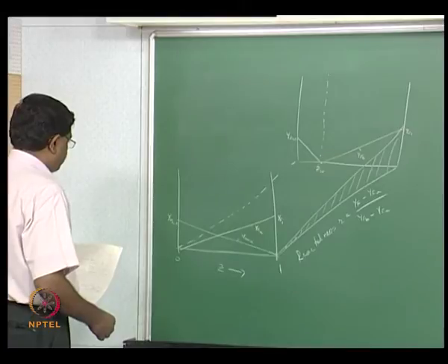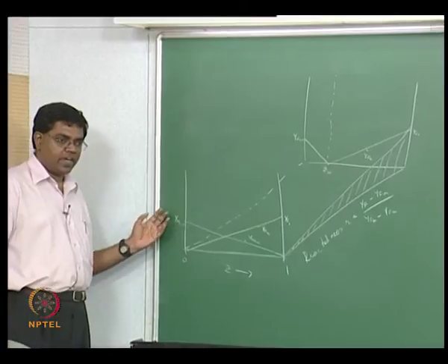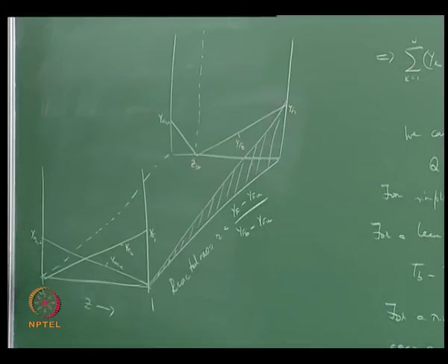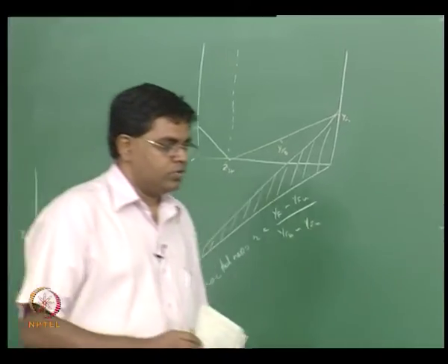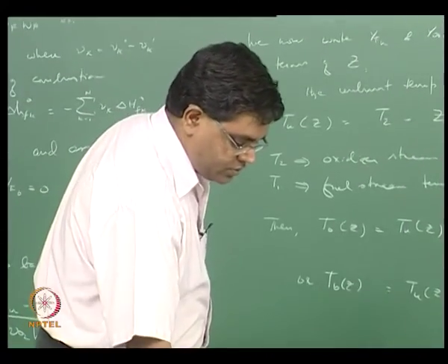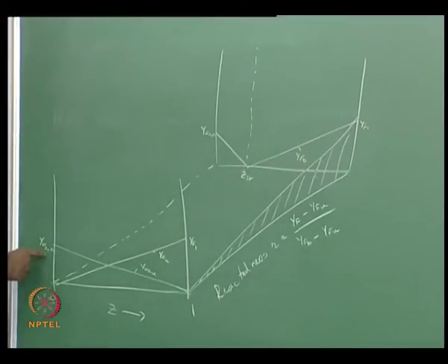And then we could do a couple of things. One, let us assume that you have diluent only in the oxidizer, like in air. So the more the air, the more the oxygen, and correspondingly more diluent. If you don't have any air, you don't have any oxygen, you don't have any diluent either. So you could think about a diluent concentration that grows with more and more O2 as we go backwards in this axis, starting from 0. So this is like YDU, where D is for diluent.